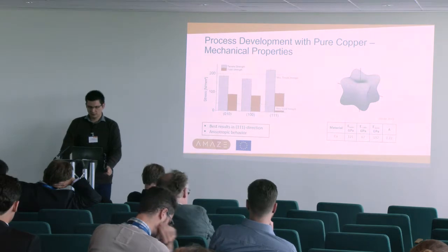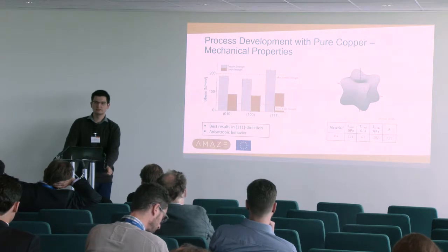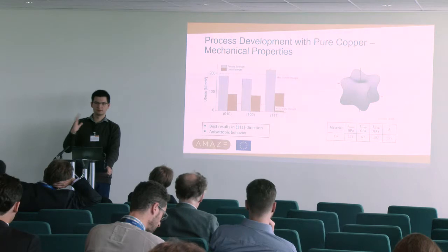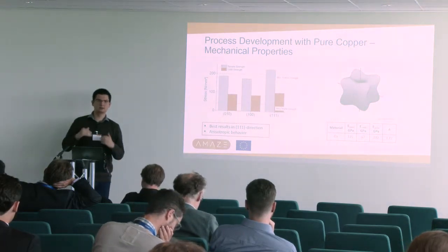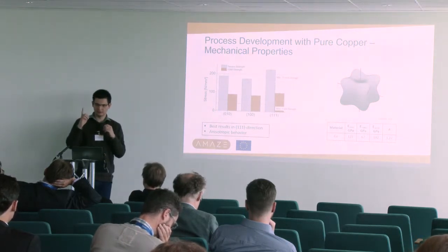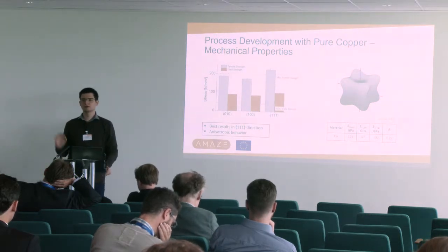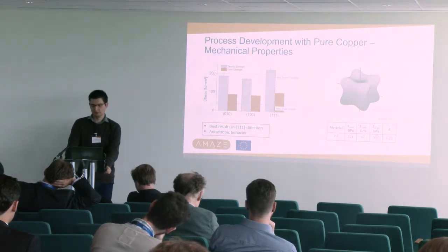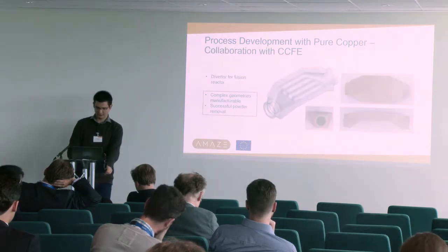With electron beam melting, we also have the possibility, which we showed with other alloys, mainly nickel-based alloys, that you can also tilt your structures. So by controlling the process so that your temperature gradient while solidifying is not pointing directly upwards, but in some tilted direction, this gives you a freedom of some degrees. It could also be applied here, but you need to consider it when building parts from it.